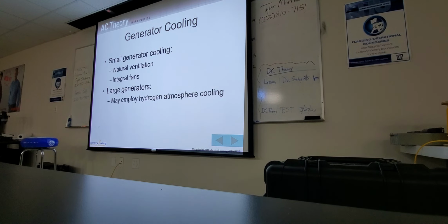Alright, so with all this voltage being induced, we're going to create a lot of heat, right? So we've got to keep our generators cool. It's done, in small generators, by natural ventilation or built-in fans. In large generators, they may employ hydrogen atmosphere cooling.